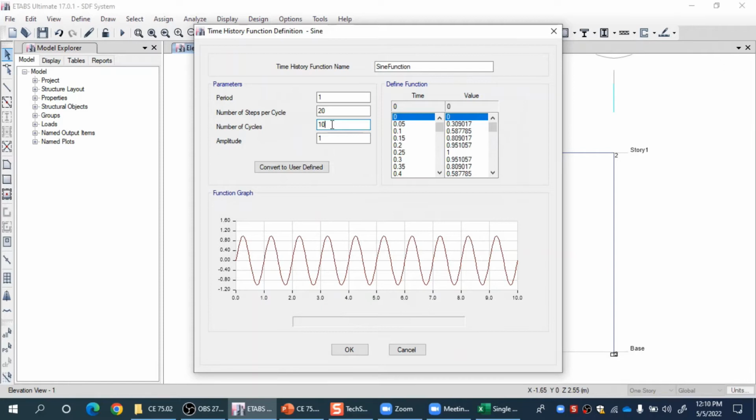So if you have an eccentric motor installed on your structure and the time period of your structure is 5 seconds, you should go for maybe 50 or 60 or 80 seconds of time history, so that the building has enough time to develop the response, or build that response if it wants to build. That will be the correct way to perform dynamic analysis.